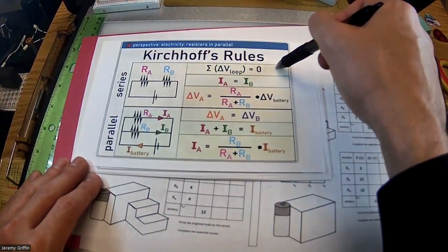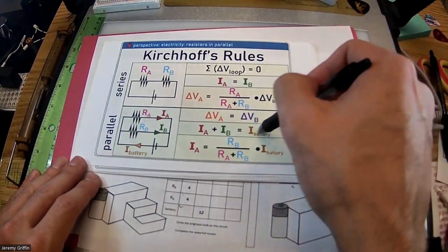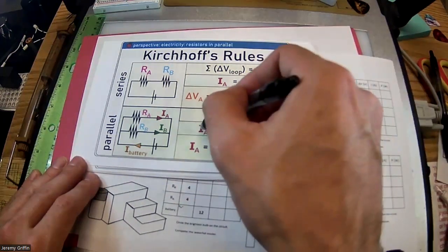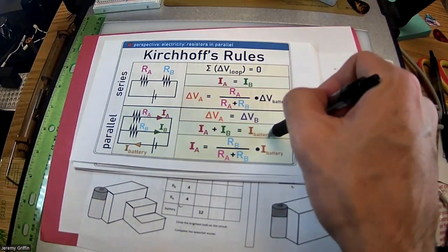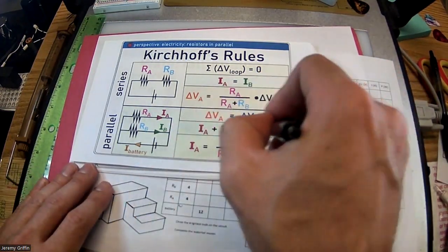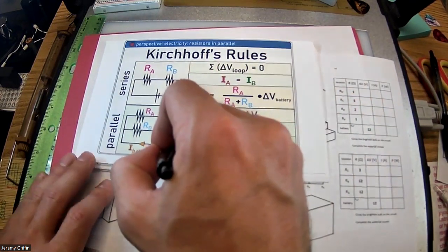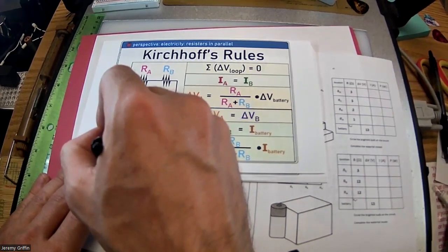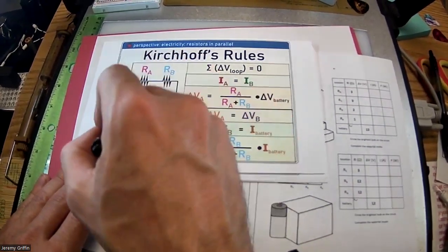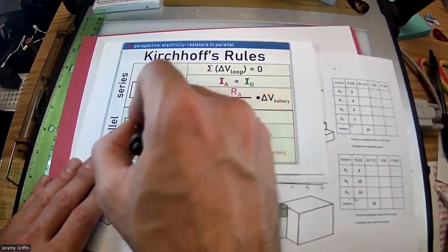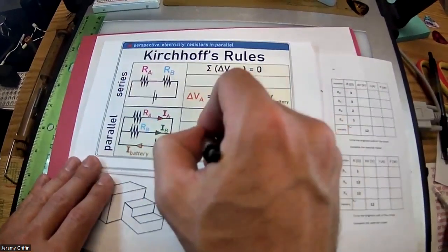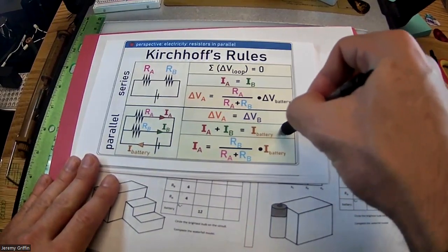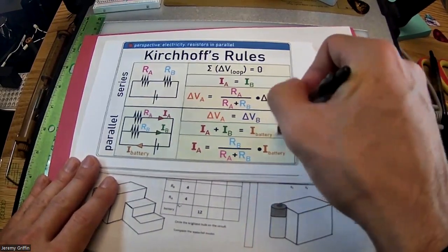Okay. Kirchhoff's other rule is this one right here. It's called the junction rule. The junction rule says that when the current splits, it has to add up to the original current. So I'm down here in this parallel setup. So say you had like 9 amps, for example, and maybe it splits. Like 6 amps goes this way and 3 amps goes this way. But 6 amps plus 3 amps still adds up to the original 9 amps. That's related to conservation of charge. Right, so those are 2 main rules.